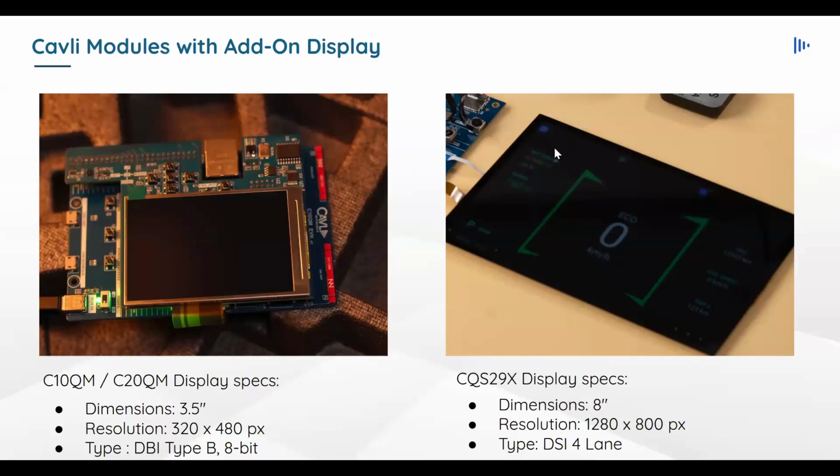Okay, because I don't really understand too much about level 5 or level 3, what you're saying. So what is the accuracy level which we can get with a C10QM when it comes to location? I'll give you accuracy figures of C16, C17, and C10QM. So C16QS can give you an accuracy of less than 2 meter CEP. And when coming to C17QS, if it's the GNB variant, it can go to less than 1 meter, and the C10QM can give you an accuracy of less than 2 meter.